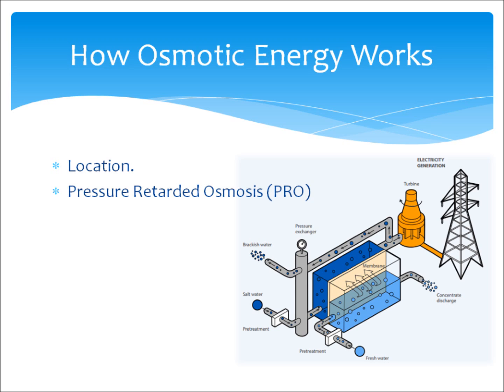Desalination plants utilize reverse osmosis, which operates against the osmotic force. The salt water and fresh water are separated by a semi-permeable membrane, which must first be filtered and pre-treated to better optimize membrane performance. Natural osmosis causes fresh water to move through the membrane to a higher salinity side. Membranes must have high water flow and salt retention capabilities. The movement of this water increases the pressure on the side of the high salinity. The increase in pressure and volumetric water flow then is used to spin a turbine, creating electricity. This can be seen in the diagram on the bottom right.